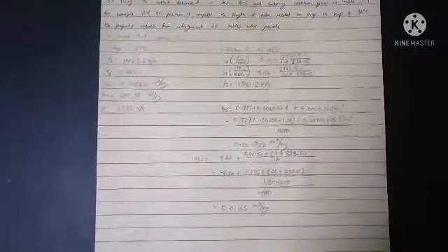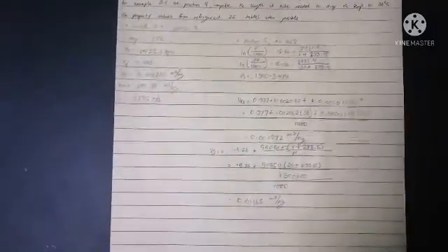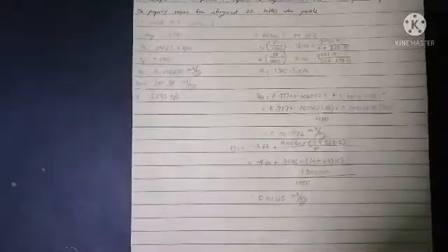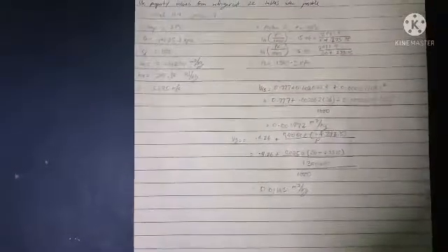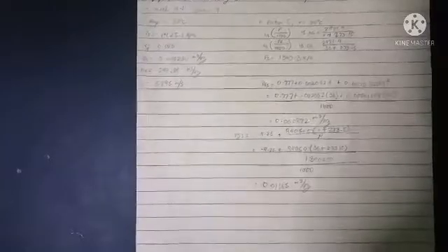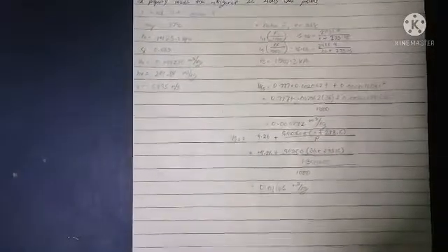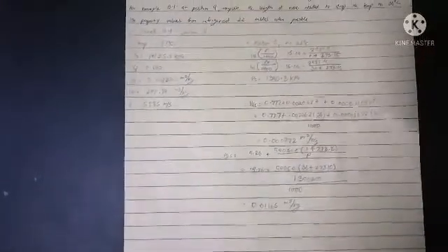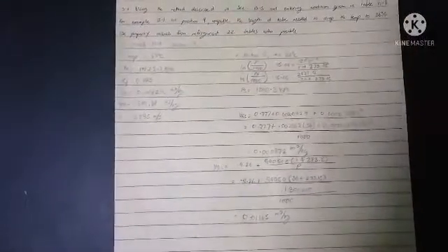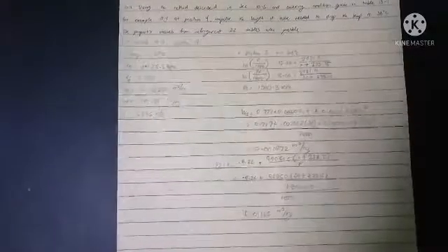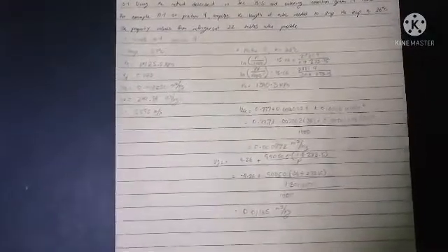So at Table 13.1, position 4, temperature is 37. So our P4 is 1425.8 kilopascals, our X4 is 0.023, and v4 is equal to 0.001230 cubic meter per kilogram. Our h4 is 249.84 kilojoules per kilogram and our V is 5895 meters per second.